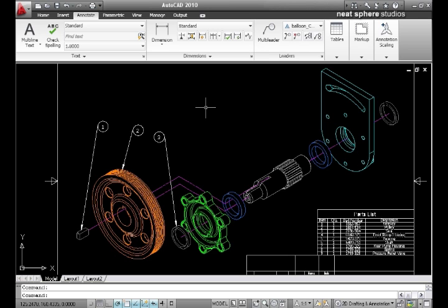One thing that is worth looking at is the fact that these aren't really aligned at the moment, so I might want to start thinking about aligning them. We've got an option here called Align. If I click on that and leave it for a few seconds, it shows me a little example. So I'll click on the align tool, and then I'll select the multi-leaders that I want to align. And there's the last one, number 1.